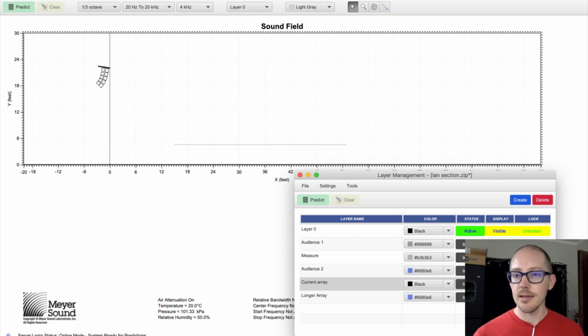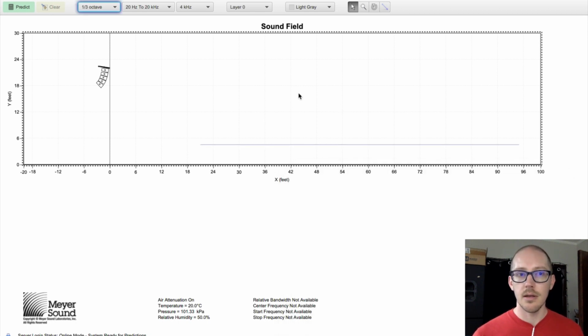And let's look at the longer audience plane, your rental plane. Okay, initially, some red flags are coming up for me because I'm seeing a pretty far front-to-back distance ratio, and I'm not seeing very many boxes here. Designing for shorter line arrays is definitely more challenging, so it's no wonder that you've been trying to figure out how to improve this and why you reached out to me.